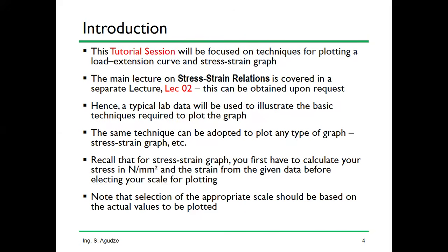So hence, a typical lab data will be used to illustrate the basic technique required to plot the graph. The same technique can be adopted to plot any type of graph, whether stress strain graph or whichever. But remember, if it is stress strain graph, then you have to calculate the stress using force over area, or original area of the bar, and then calculate the strain, change in length over original length.